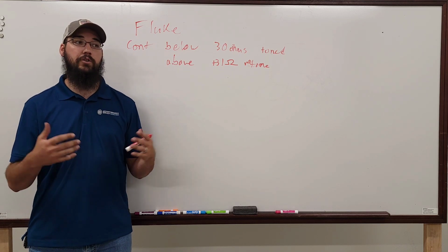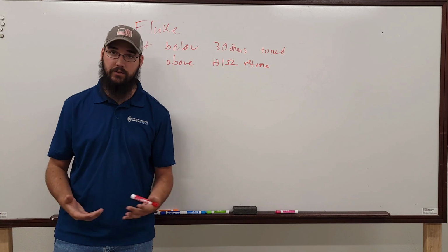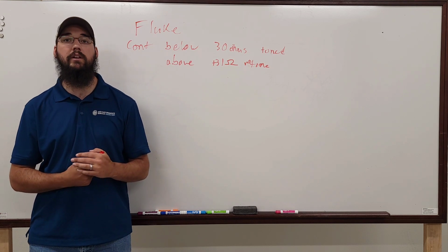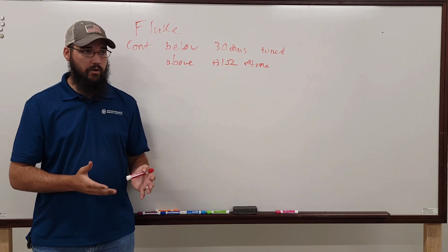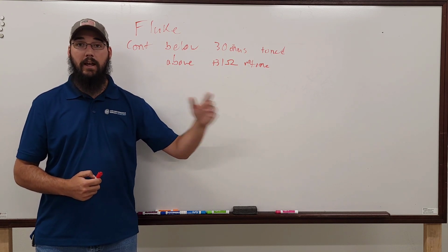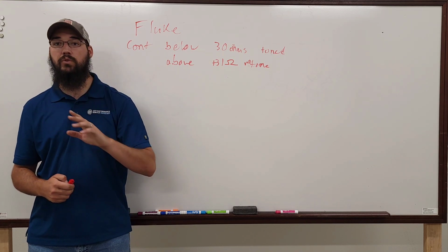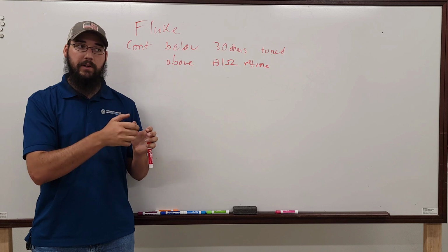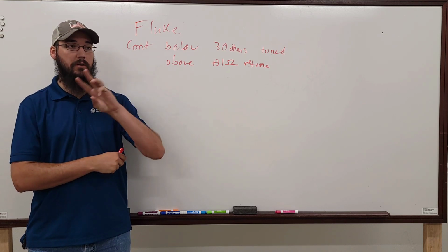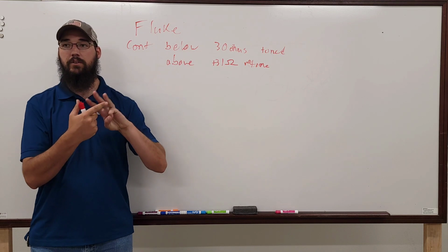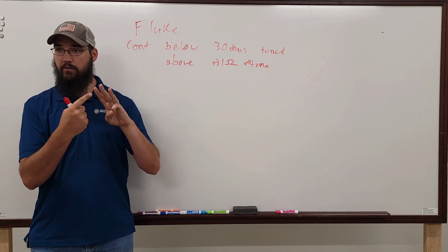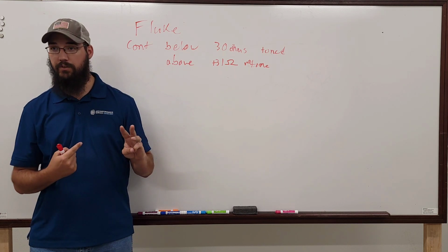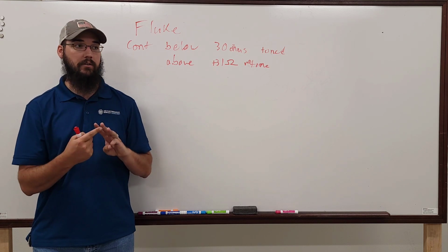But if you're going in and you're just doing general tests and you're analyzing a system and you don't know that there's a short, you just want to see what the readings are, continuity is not the direction to go. You have to go into ohms. And even when you go into ohms, you have to use the proper range. I've seen this before with technicians. They put their meter in manual ohms, and usually most of your digital meters will have 3 ohm settings. It'll be M ohms for millions of ohms, K for thousands of ohms, and then just regular ohms, which the moment you get above the thousands, it's automatically going to show OL.